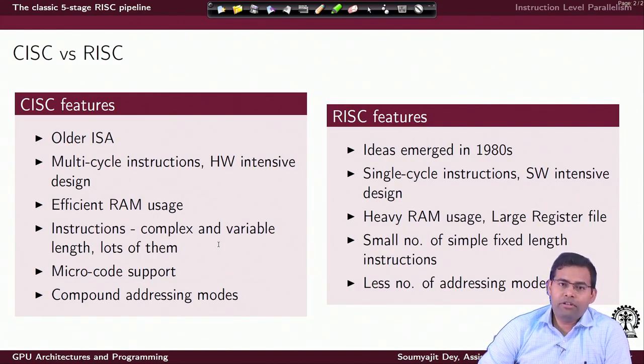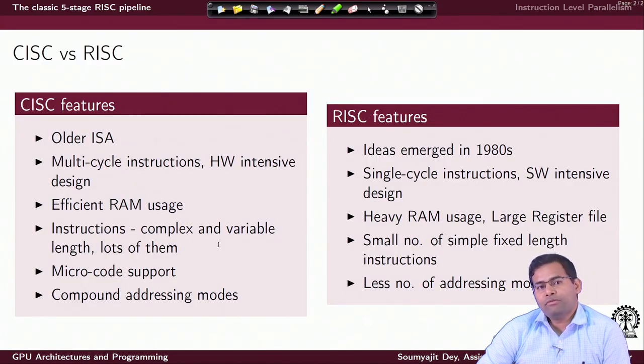Now, another very important thing is, since there is no regularity in terms of the intensiveness of CISC instructions, some instructions may be very complex, take multiple operands, take multiple cycles to execute, and due to their inherent complexity in terms of specification as well as number of operands, the instruction encoding length may be very big, whereas for some other CISC instruction, the instruction encoding length may be small.